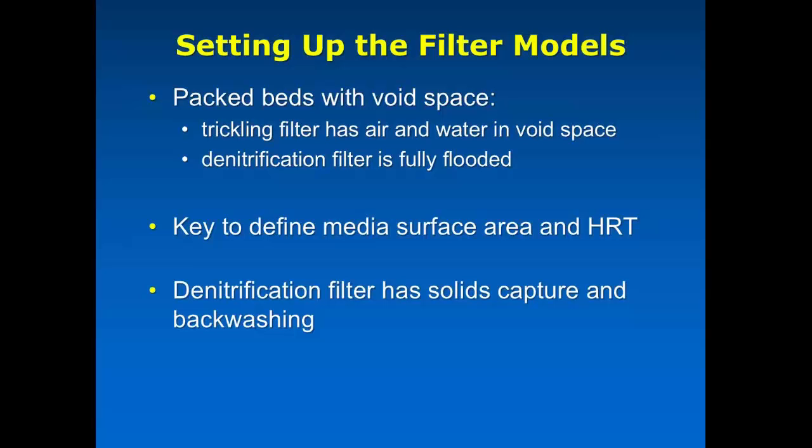In addition to that, the denitrification filter also has a solids capture, because we wanted to be able to capture the performance of the filtration going on, but without going into extremely large amounts of detail of trying to model the filtration in a dynamic sense. So you specify a solids capture and a backwashing rate, and then we figure out how much solids come out of that system and put that out through the backwashing connection point on that object.